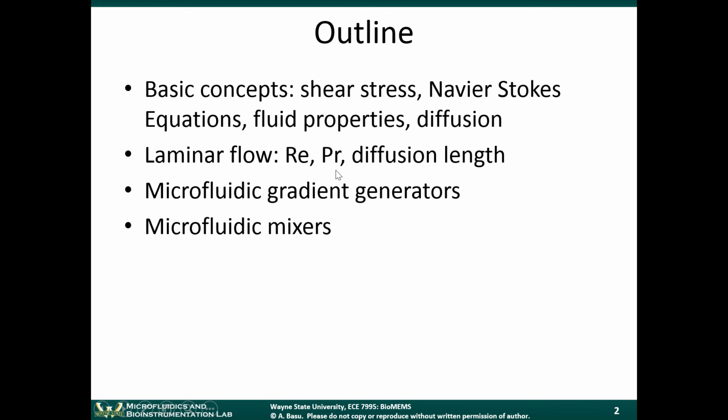So one of the things about microfluidics is that because you have laminar flows, you have the absence of turbulence. In turbulent flow, the fluid sort of rolls and folds into each other, sometimes in unpredictable patterns. Turns out that's very good for mixing. But in microfluidics, you have laminar flow, streams running parallel to one another. This is not very good for mixing. If you want to mix, you want the fluids to be turning and folding upon each other. So there are ways that you can enhance that rotational motion of the fluid to encourage mixing.